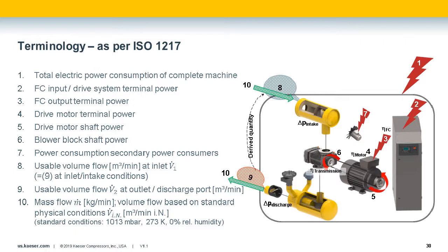But hopefully with this we can see how the numbers from the blower supplier need to be accurate and representative to give a real evaluation. If we're just doing our evaluation based upon blower shaft power, we are losing out on all these points 1 through 7, including our losses in the drive, our losses from fan and silencers, as well as consumption of power in the electrical cabinet.